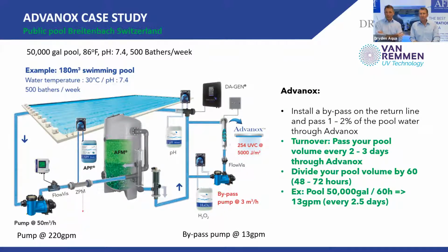Let me really point this out. This was exactly right. Oxidation demand is not that important. It's really about the organic chloramines. 80 to 90% is organic chloramines. Because of Daisy, we have very low values of inorganic. Inorganic, as you said, can build up in minutes, in hours. But not organic chloramines. They build up slowly over days. And this is why it's absolutely okay to treat the water once every 2 to 3 days.